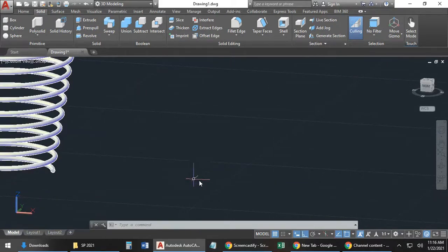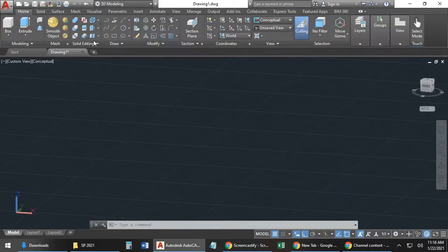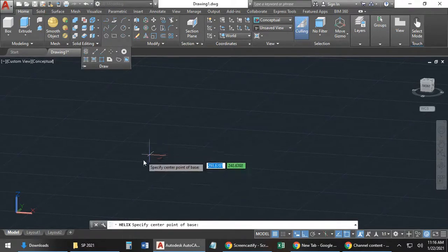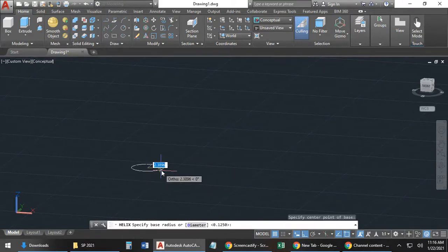As we look at doing this to create threads, we're going to bring up the Helix coil again. In this particular case, we're going to make sure that our bolt is the same diameter at the top and the bottom. We'll do a sample one here. Let's say, for example, a quarter 20 bolt. That's a standard size. The major diameter is a quarter of an inch, or 0.25. The 20 stands for how many threads are in 1 inch, so that would be 20 threads per inch.